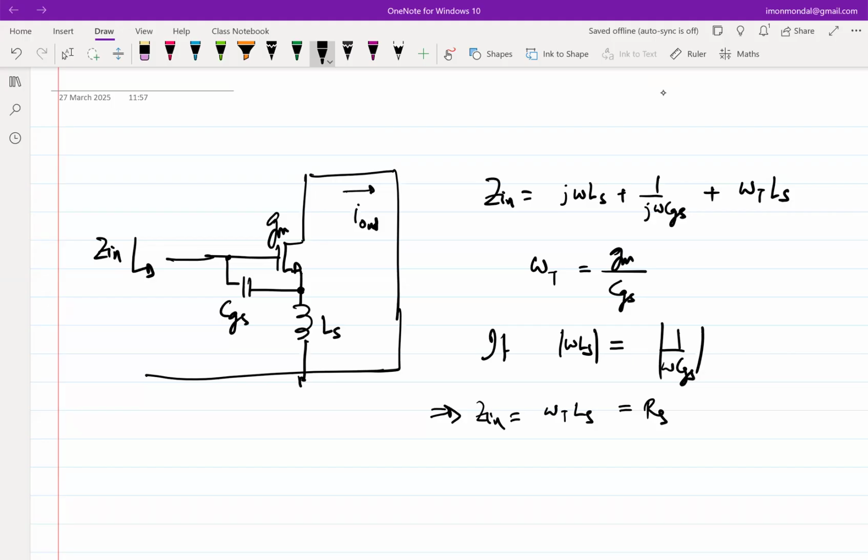So today we are going to look at this in a bit more detail and see whether there are some nuances to it, or we can simply say that, okay, this is it, right? When you are designing, you then have to ask the question: this architecture probably seems to work, but how do I size the transistor? How do I size CGS? How do I size LS? So before doing that sizing business, let's look at the fundamental thing that an amplifier is supposed to do: can it give us gain? And if it gives us gain, what is the gain that we are going to get? And if we want to maximize gain, what are the handles that we have?